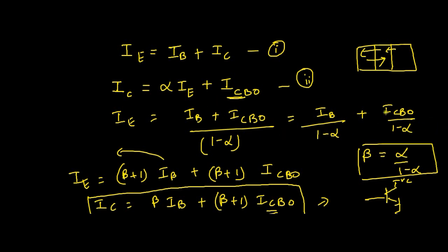In the coming videos, we'll deal with the stability of the BJT. As you can see, this is the BJT characteristics. You choose the operating point, IC1 VCE0. The operating point which you fix should be stable enough. It shouldn't move. But since this current is largely dependent upon temperature, the operating point may move here, it may go into cutoff and all.